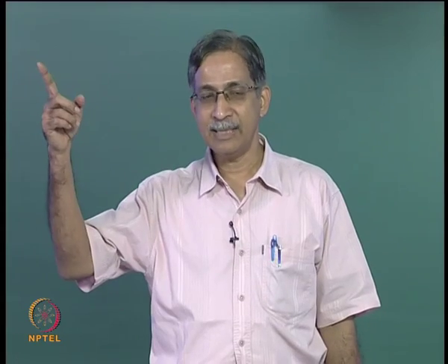Is it a sinusoidal shape, etc. It only tells you the shape, nothing more than that, which means it tells you, let us say, at the mid height of the column, what the deflection is in relation to the top. Those ratios are maintained. That is what we call a mode shape, and the first mode shape looks like this.